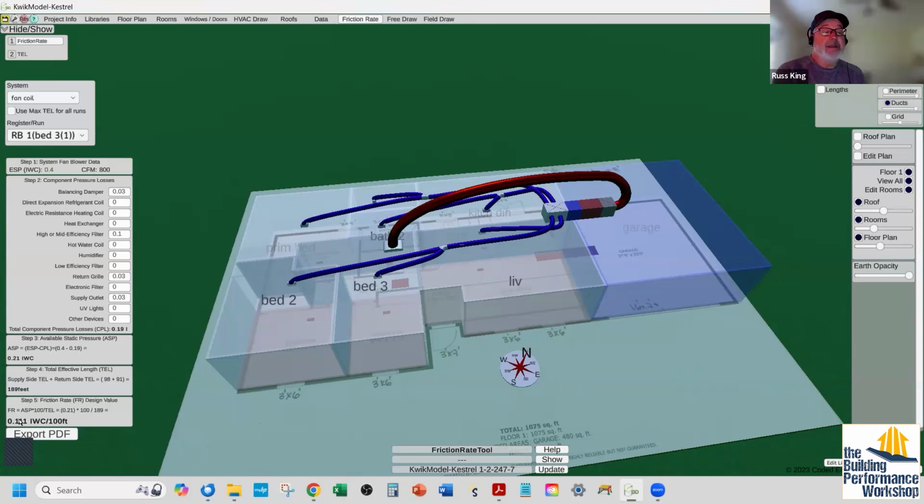Isn't that right? It's not against Manual D. That's the old way of Manual D. That's the way Manual D used to do it, and it still does. But Manual D also says that you can use a custom friction rate for each one, but that it's a lot more work. Well, with software, it is no more work at all. Right, it's zero work. You've got to press the button though. So yeah, I encourage people to use custom friction rates when they can.